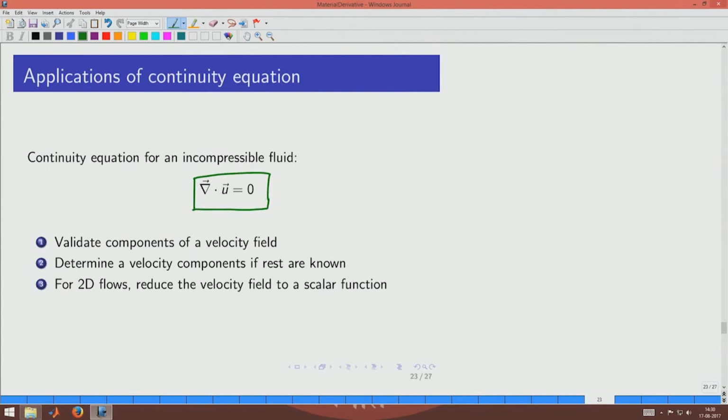First thing is that velocities are basically vectors, and we already know that there is one check we have to verify, whether it is a vector or not, and that is the definition of a vector, that is, a tensor of order 1. Once that passes, we need to see whether that velocity is a valid vector for describing the fluid flow subject to the mass balance, which means you could plug in any velocity field you have and check whether the divergence is 0.